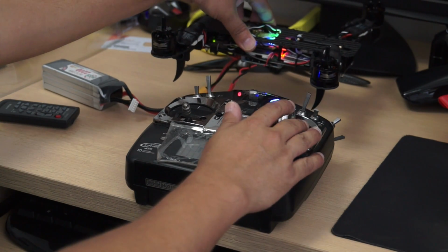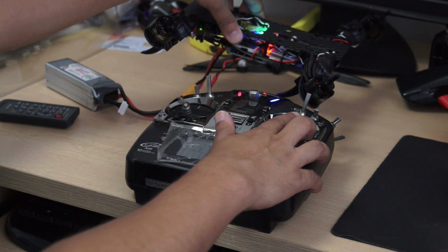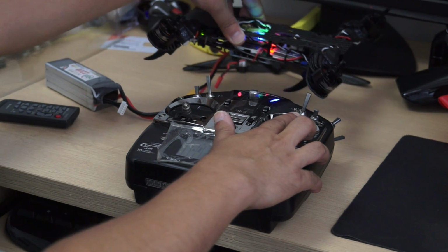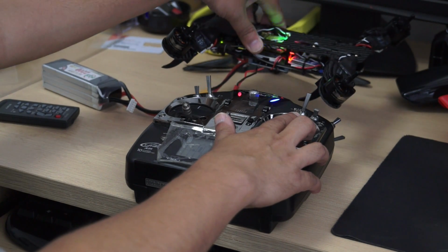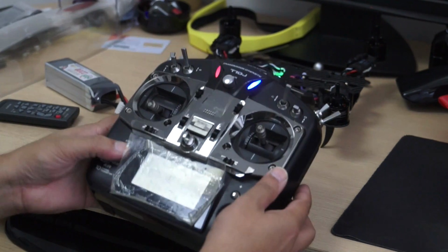Now if I turn both of these mixes on, what is going to happen? If both mixes are on, when I push forward, rotors will tilt more, quadcopter will tilt a little because of the reduced elevator effect mixing, and quadcopter will fly really fast, completely leveled using the rotor tilting only. So I hope this concept is clear.